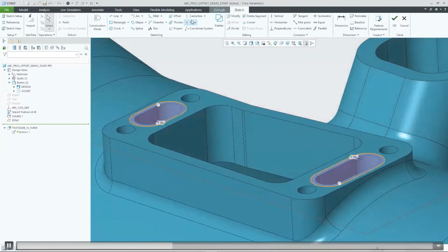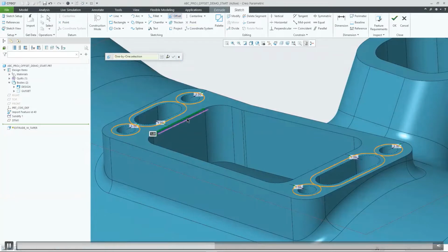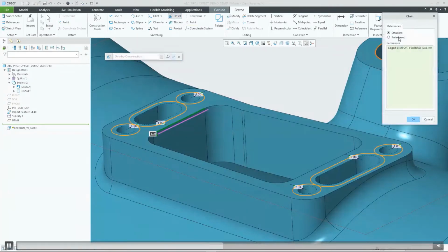The following example shows a similar workflow referencing 4 circular loops as input to the offset tool. Press the Apply Repeat button to apply the current selection, leave the UI open, and continue with another reference chain selection. Users that prefer the detailed chain collection UI can also invoke that and define the chain rules, options, and references there.